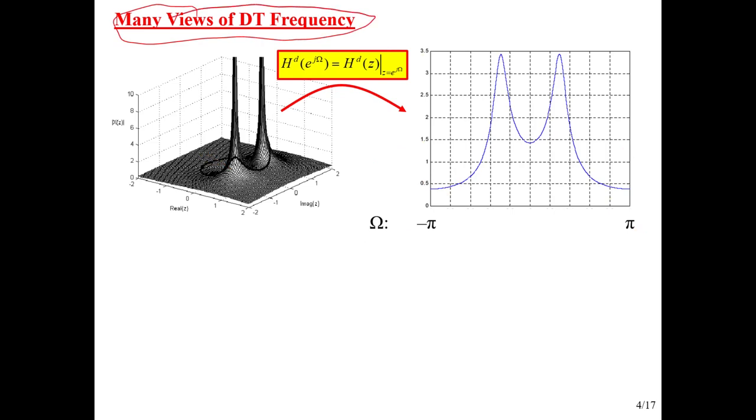So this is a convenient variable to use when we're just talking theory, or maybe even just worrying about some sort of design issues. But this is in radians per sample, and it has no connection to the physical real world. Remember, we want to see, how does this filter mimic the desired analog filter? So we really need to connect these discrete time frequencies to the physical real world. And so that comes through the sampling rate, right?